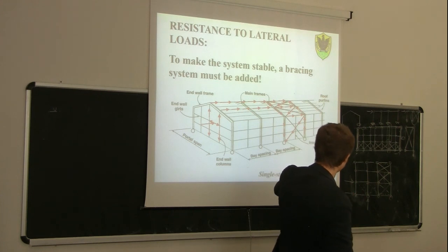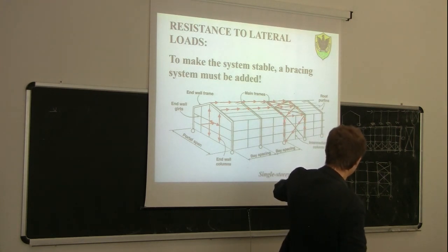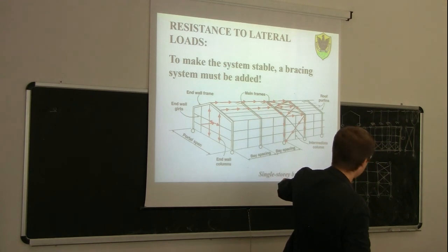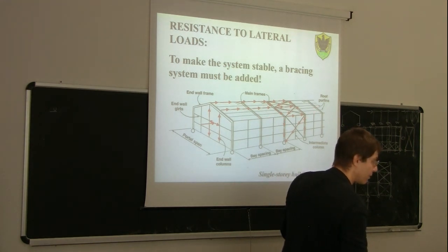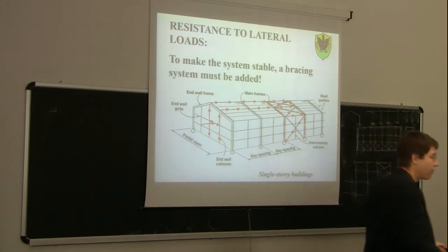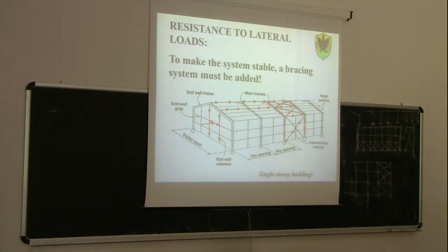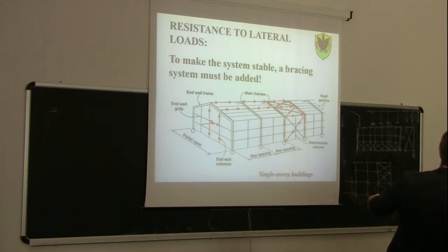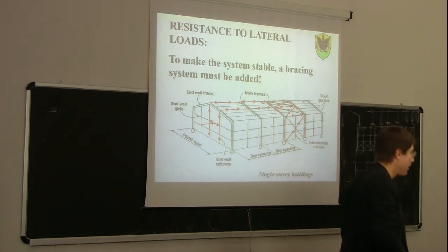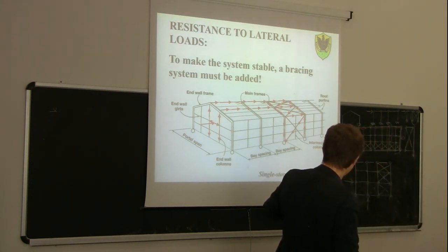Just note that in this bracing system, it's not only the diagonal that works. So the diagonal will work in tension. If we use, for example, rods, the rod will only resist tensile forces, not compression. So some of the diagonals will be stressed in tension. And those diagonals will contribute to bring this horizontal force down to the foundation. But note that also there are some forces going down through the frame, compression, and to the other frame, tension.